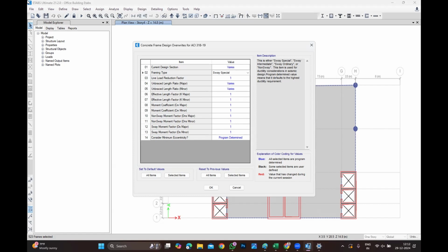Because of this lack of knowledge, people think: whatever information I have given to the architect, I cannot go back and change. That's it, then I will play with the reinforcement. You see sometimes 6%, 7%, 7.5%. But this could be solved in two ways: either you increase the grade of concrete or increase the column size a little bit. People are hesitating to talk to the architect, or lack the knowledge. You get what I'm trying to say.